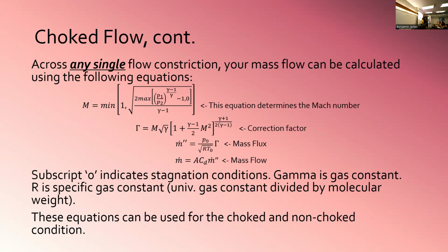This mass flux condition, if you increase your upstream pressure, then you will get a higher mass flow as you have more mass packed into a smaller volume. What choke flow dictates is that you can only have so much volume travel through that orifice, but if you have an increase in your upstream pressure, you pack that mass into a smaller volume, you get more mass flow. However, a decrease in the downstream pressure does not affect the upstream volume intake, so no change in mass flow.